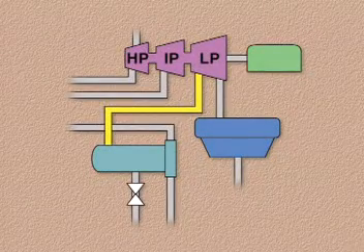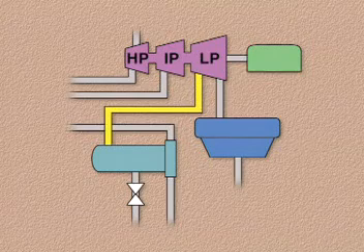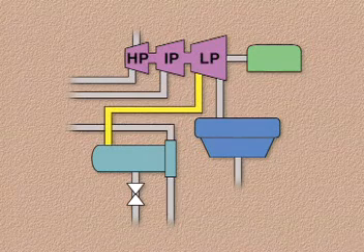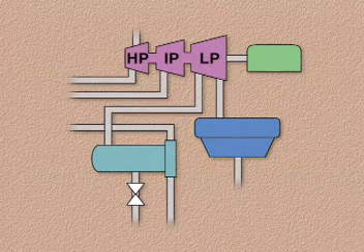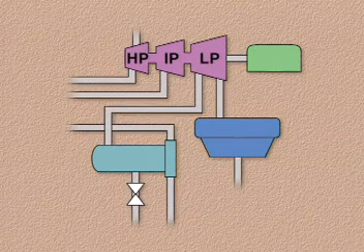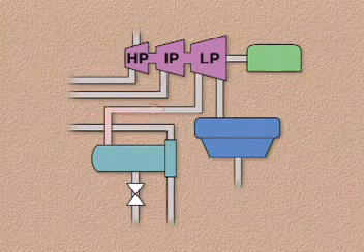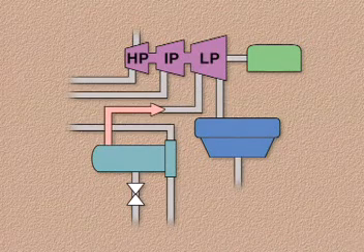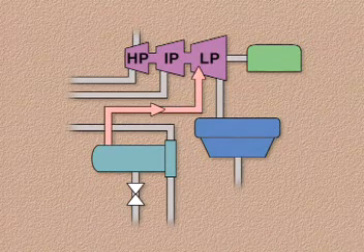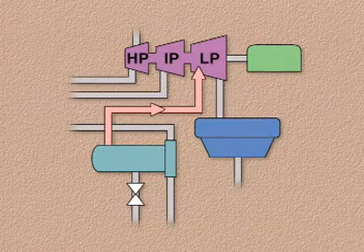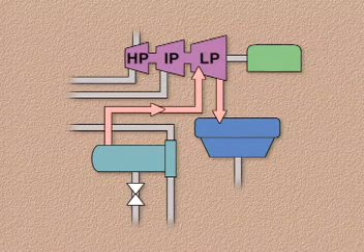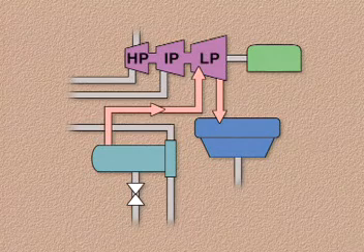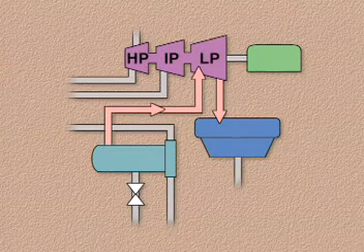Low-pressure extraction steam lines in which steam pressure is less than atmospheric pressure may not have valves. Backflow and high heater level aren't of much concern in this situation because these conditions are unlikely to cause problems. In the case of backflow, the low-pressure steam usually passes through only the last few stages of the turbine and then exhausts into the condenser. Under these circumstances, there's not enough steam involved to overspeed the turbine.